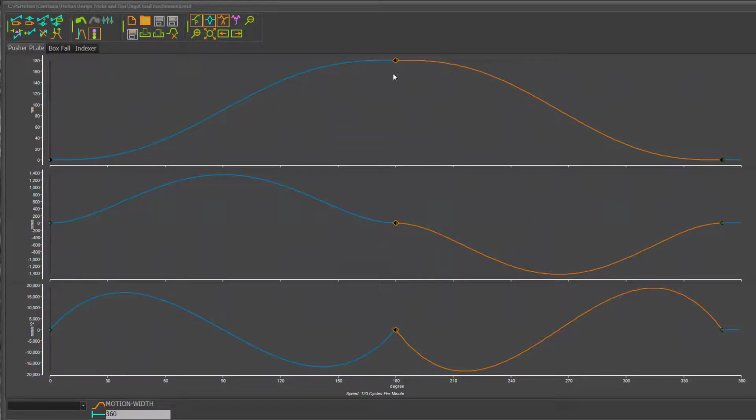So if we look at the motion at this node, we've sort of got a pseudo dwell, because do we really mind if the pusher moves by a small amount? Not really, because we know that if it's only moving a small amount, it's effectively a dwell. But perhaps we can make this pseudo dwell even more exaggerated, or lengthen it, by using the trick that we used before, controlling the jerk.